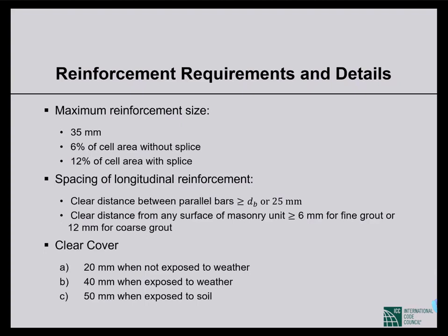We need to have adequate clear cover so that the reinforcement doesn't corrode with time, and it depends on the weather condition, the exposure condition.